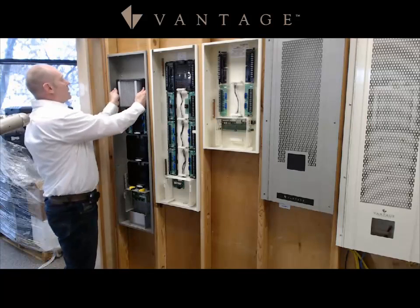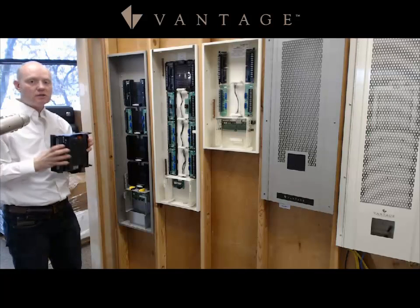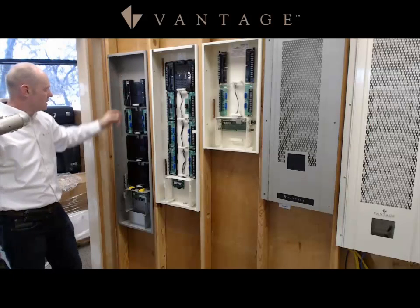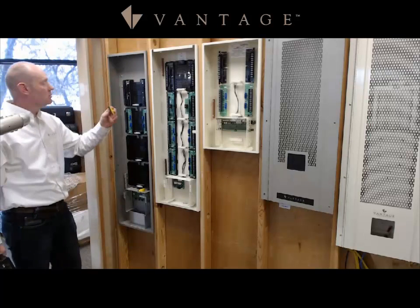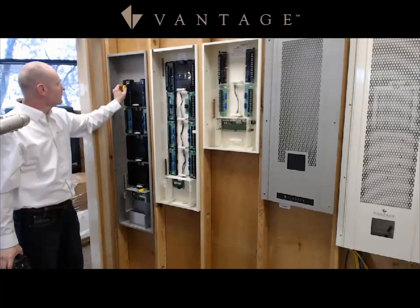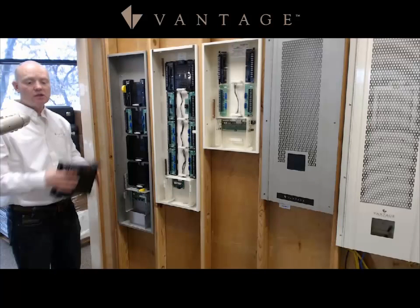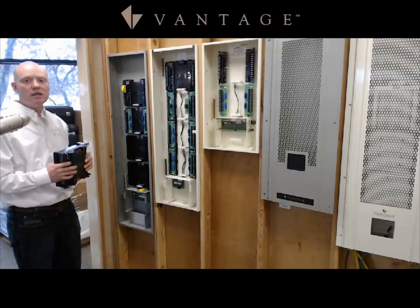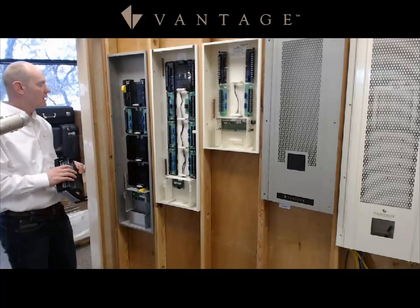By doing this, you're able to land all of the loads on the enclosure boards, and then put the jumpers into place and run those just by flipping the breaker, and then you don't have the expensive part of the modules out on the project until all the fixtures have been tested and you know that they're working correctly.